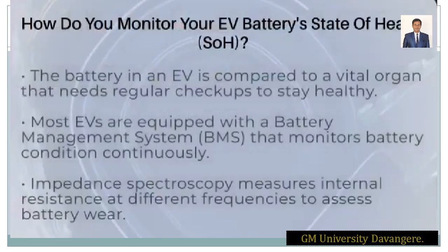So that gives you 100% of base voltage in the initial stage. After the aging stage, the same cell has aged now. So the aged cell, when it comes to around 90 milliohm, means the resistance has already increased from 50 to 90 milliohms, then the SOH will also decrease. That may come to around 70% SOH.